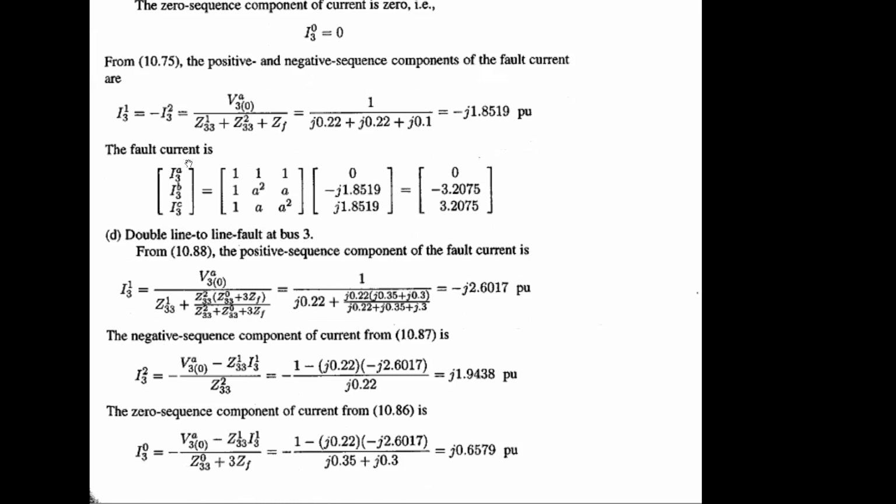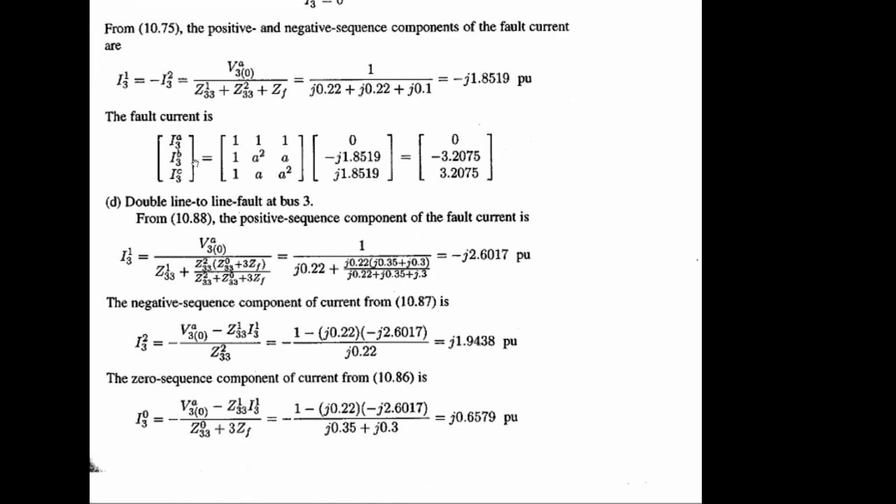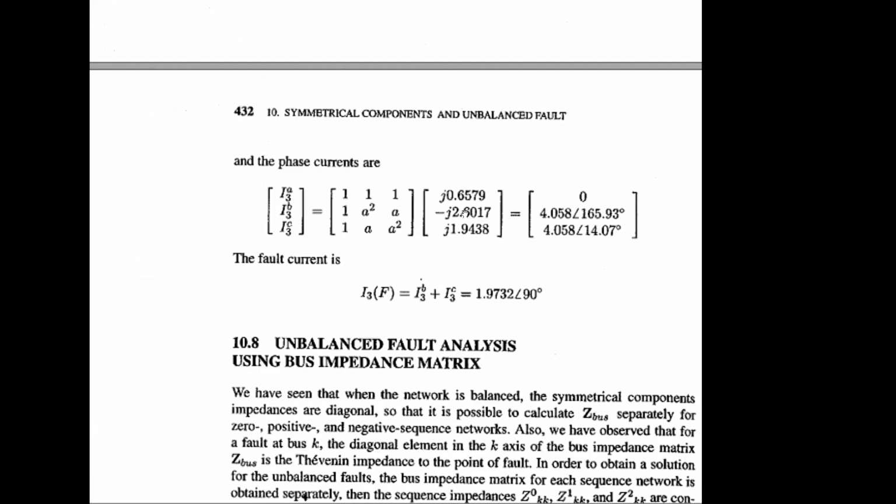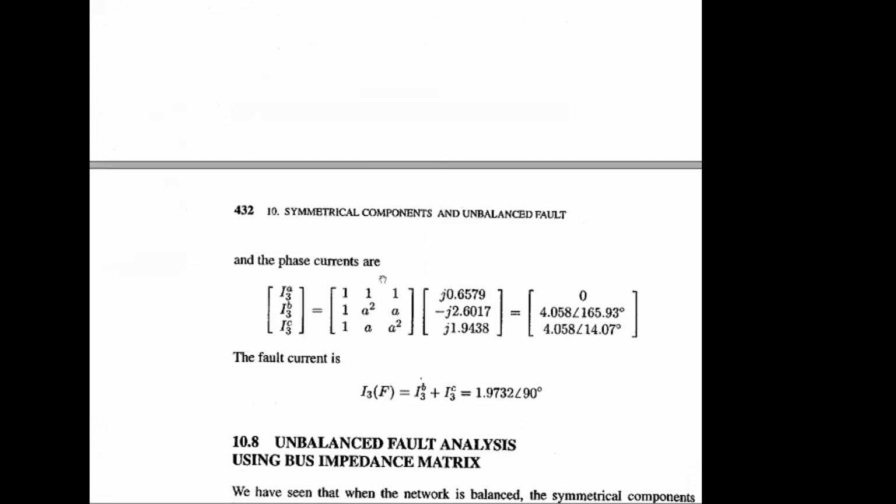For current calculation, the first step is to determine the fault current for all the scenarios. And when you complete this fault current, you have this part as 0, 1, 2, and this side is ABC in terms of I3. So after completion, you can get the total fault current for double line, which is I3B plus I3C. This part is for double line to ground fault. For other faults, you can use only IA information.